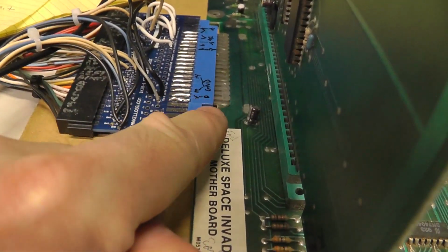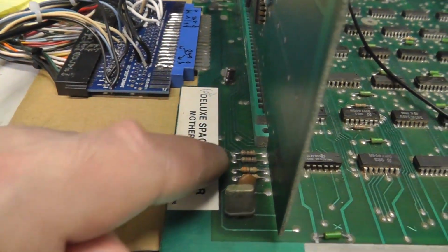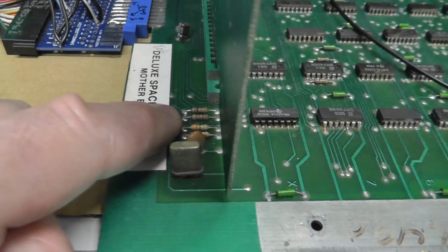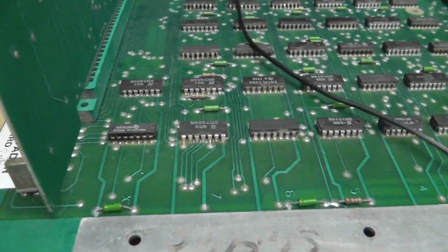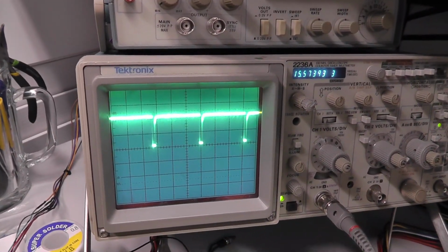So there's our video right there of the game board powered up. It comes to this cap. The positive side of this cap comes to these two resistors here. Here are the two 1K resistors. I measured those. But by the way, I have it on, and you can kind of see I'm running unit under test, and you can kind of see the white lines vertically. I know that's kind of tough to see, but you can see the lines, except it's all white. And if I come to pin 6, that's what we look like on the scope.